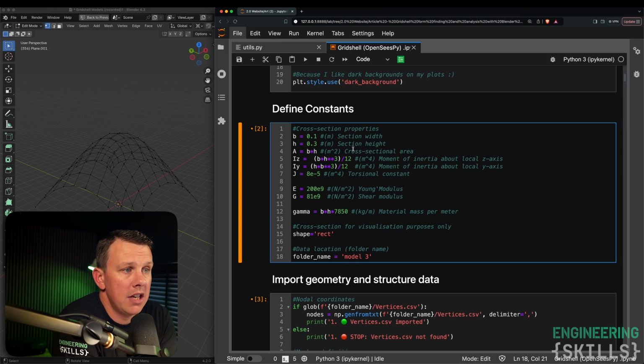You have to essentially lock the joints and solve it using a frame model. So this is very analogous to, if you imagine a column, an Euler column. An Euler column will have an Euler buckling load. And in theory, if you increase the axial force on that column beyond the Euler buckling load, it will still be in equilibrium in theory, right? But it will be an unstable equilibrium.